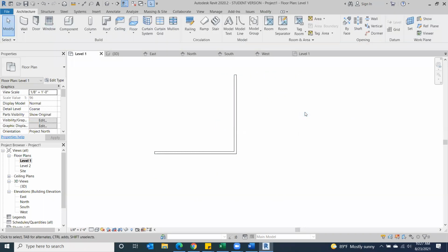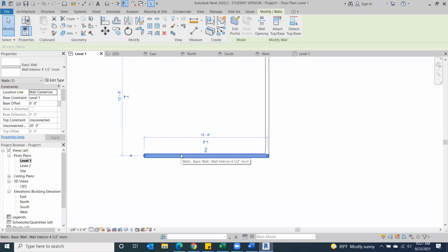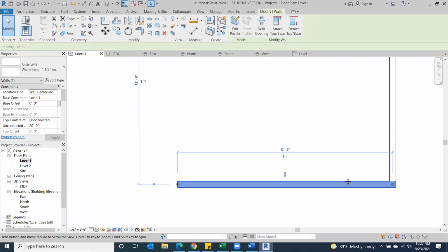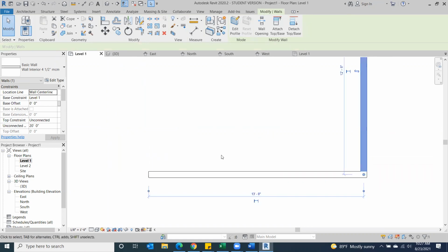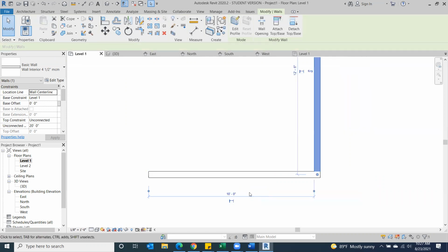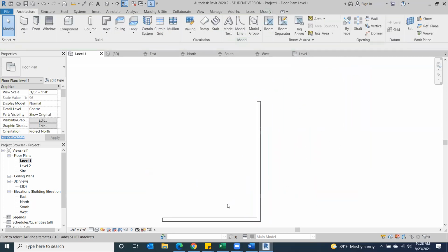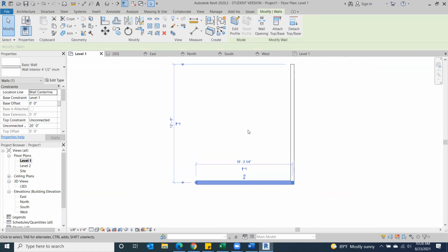And then you right click cancel, right click cancel. So notice how sometimes when we click too fast, we lose that measurement. So now I can go from my internal wall to my internal wall and set that to 10 feet. Now, if I want this wall over here, I can go from my internal wall to my internal wall and set that to 12 feet.